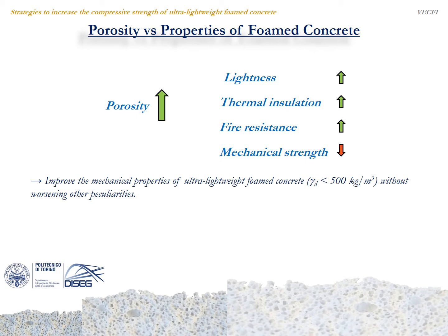These different fields of application are due to the fact that, if, on the one hand, the increase in the porosity of the material is associated with improved physical properties such as thermal insulation, acoustic absorption, fire resistance, lightness, which are, in many respects, characteristics of absolute importance in the building sector, on the other hand, the increase in porosity is accompanied by a significant reduction in mechanical performance. Evidently, the utopia is to obtain a material characterized by all the physical properties that characterize lightweight foamed concrete, associated, however, also with good mechanical strength.